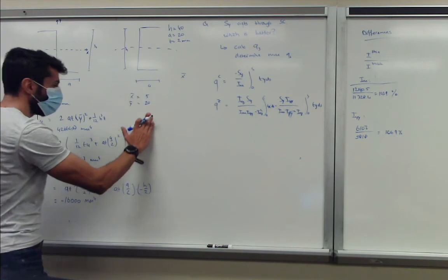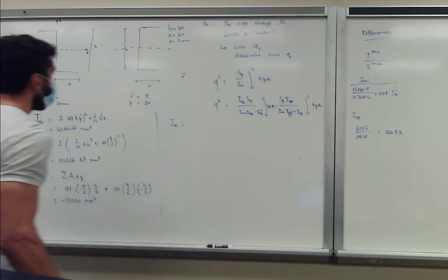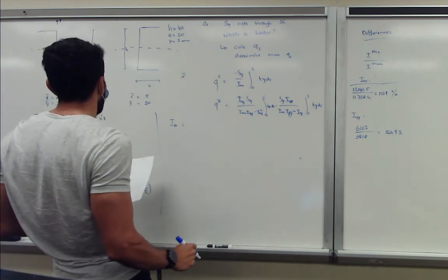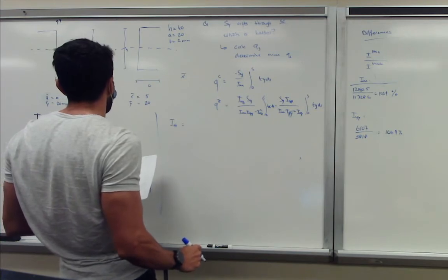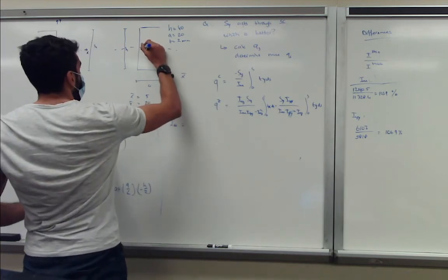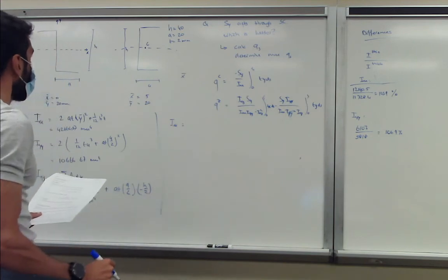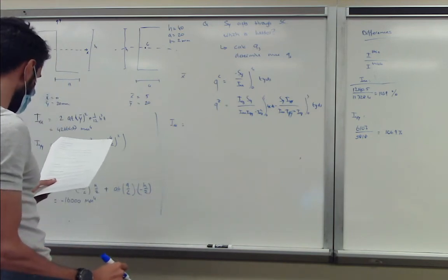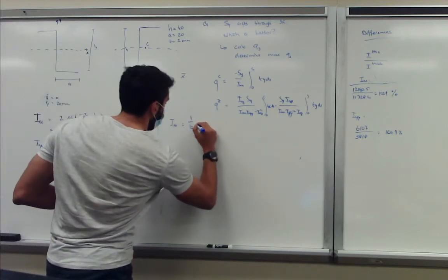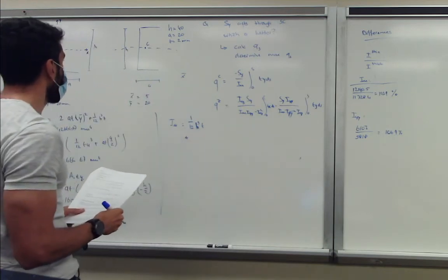And for this section, the moment of inertia, Ixx only, so that makes our lives a bit easier. Let's see. We have our centroid located here. So we get 1 over 12 H cubed T plus the two standard terms.